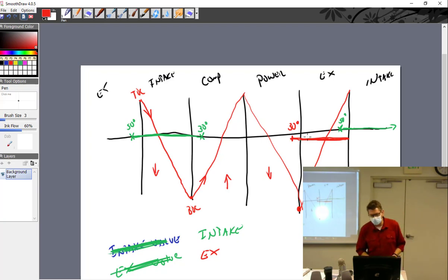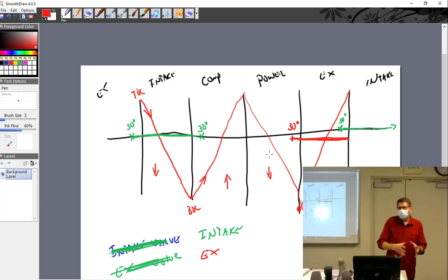But here we are opening at 30 degrees too early. Well, that sounds counterproductive. But what happens is by about 30 degrees left in the stroke, this exhaust gas is doing nothing. It's expanded or used up all of the heat energy that it's going to for work. And now all of the heat energy is going into the cylinder. So you've extracted all the work you're going to, and now you've just got, we'll call it 1400 degrees trapped in the jar, and we're just going to hang on to it in there.